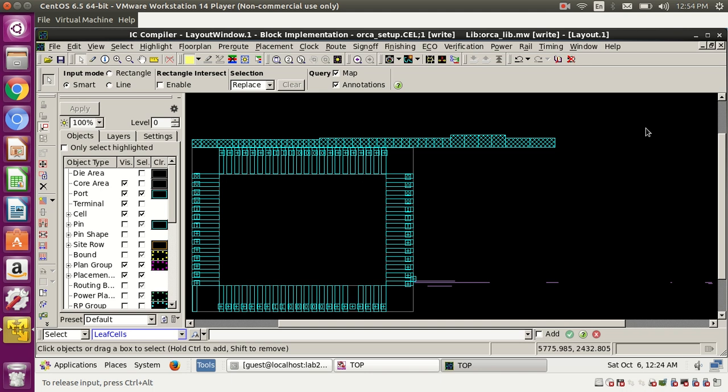If we give M1 as diagonal or some other direction, M1 will go from here to here, so the next M1 has to cross like this only. All nets would have to be diagonal, but that cannot be. Suppose we have a cell here and a cell here and they both need to be connected. If M1 is horizontal, M2 should be vertical, or they have to cross.